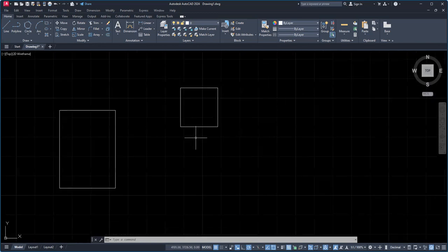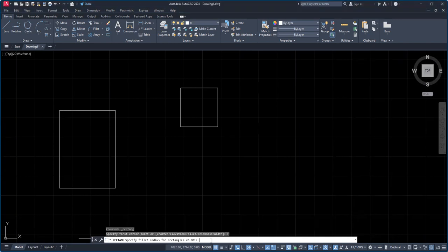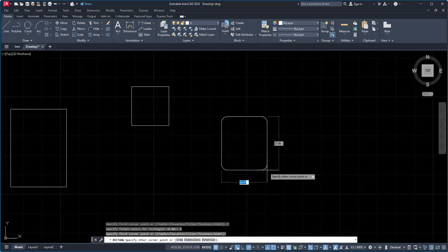Okay. So sometimes if I want to draw the rectangle, but I just want to make these corners smooth. Okay. I want to give some radius. Technically we call it a fillet. Okay. So go with the rectangle command, and in the command bar, here we have a fillet. For fillet, we have to mention the radius. Assume that you have a radius like 2, 3, 4, whatever it may be. Enter. I had given the fillet amount as 3, and then click the first corner and the x amount, comma, y amount, like 10, comma, 10.